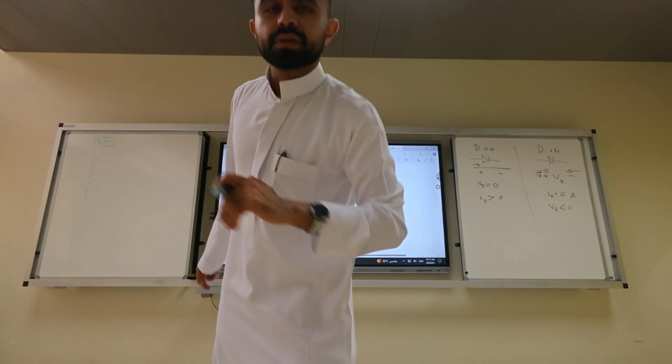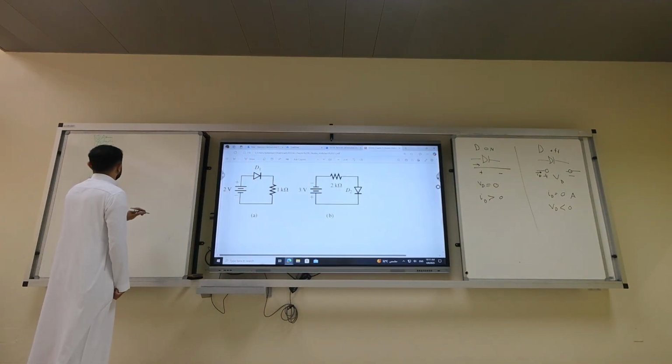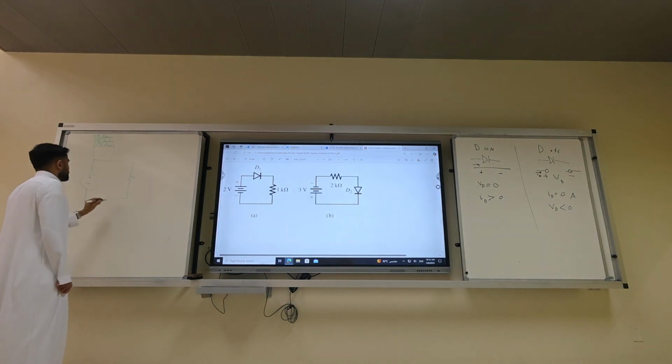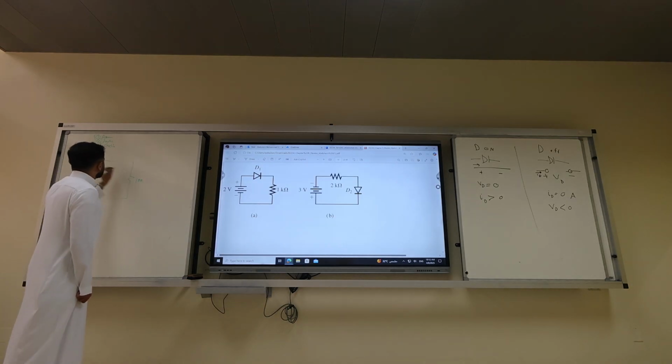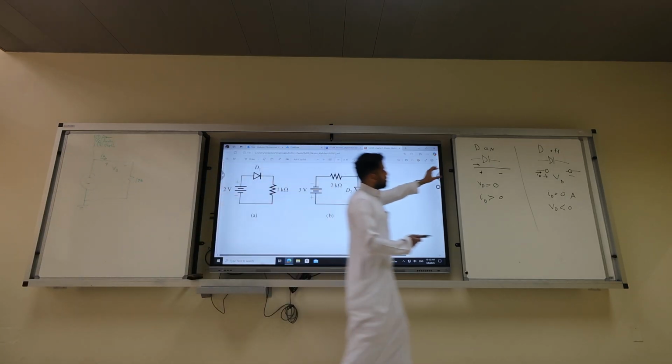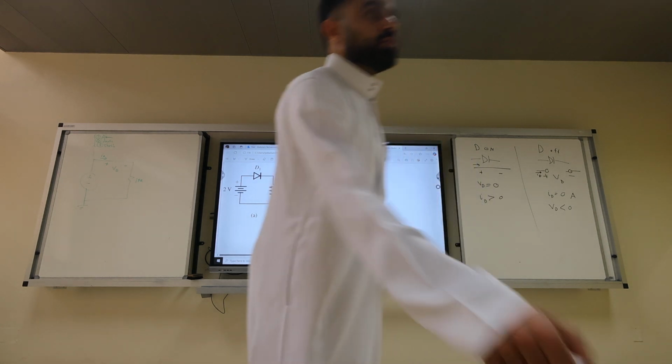Is the recording on? Yes. We said we will replace it with a short circuit. And then we connect everything else the same. Okay? The ground is here. This is 1 kilo ohm, and we said plus minus VD and I of D. You replace the diode with this component. Okay? So we're done with the assume.